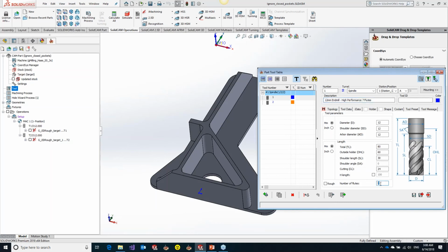So what does this mean? Now we are starting to see that tool manufacturers are making specialized tools for iMachining style toolpaths. What this means is they're meant for side step over strategies where they know you're not going to take the tool and just bury it in a corner. They can optimize the cutter geometry so it works better for these toolpaths. They can make sharper rake. They can do all these different things. And of course, one of the bigger things is more flutes.